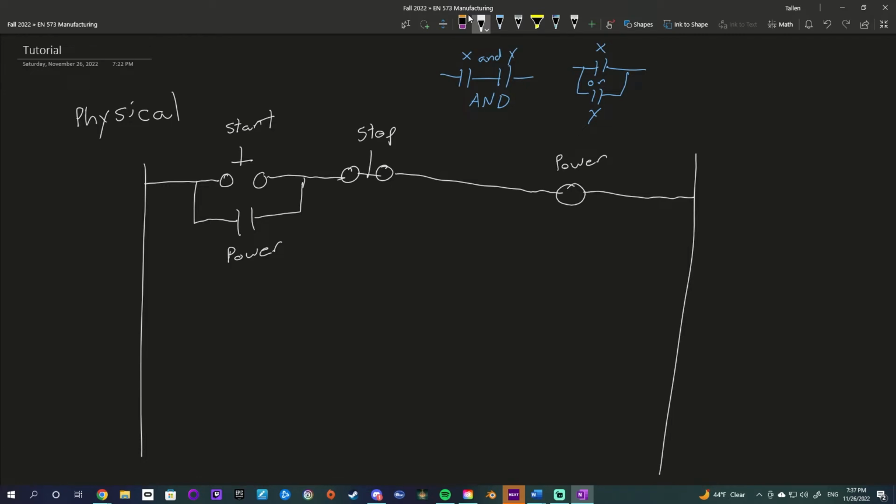Well, we want to start filling our tank because it's empty at this point. So, we can just do V in. But now we have to ask ourselves, when do we not want our tank to start filling? Well, for sure, we don't want our tank to fill when there's no power. So we're going to have a normally open gate there for power. The other time we don't want our tank filling is if our tank is full.